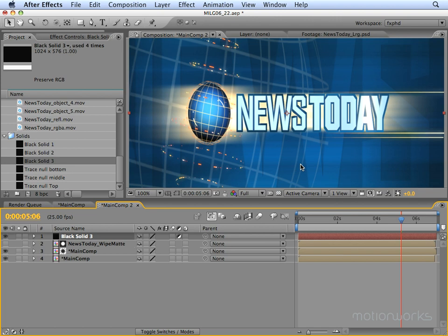relevant is the fact that a TV works like that, and because of this, and because of the thickness of the line of pixels, what can happen sometimes with very thin lines, particularly areas like here, is they may well sit between two rows of pixels on a TV. And what will happen is as it scans down, the line will flicker between the two rows. This problem is particularly obvious with very thin horizontal lines, but you'll often see it on the top and bottom of text elements, and as the text moves across the TV screen, it will flicker.